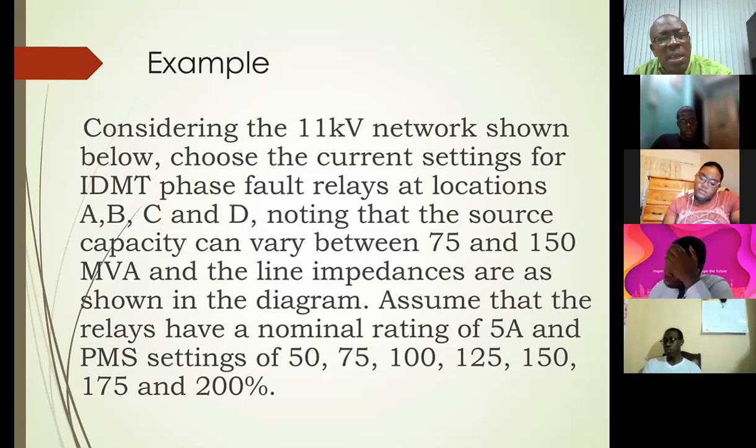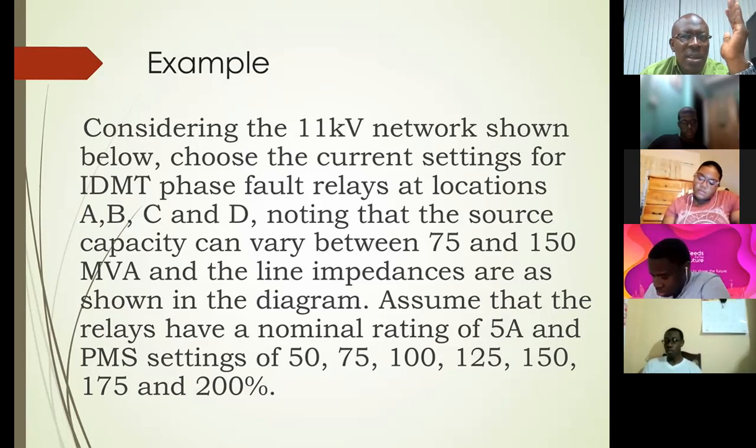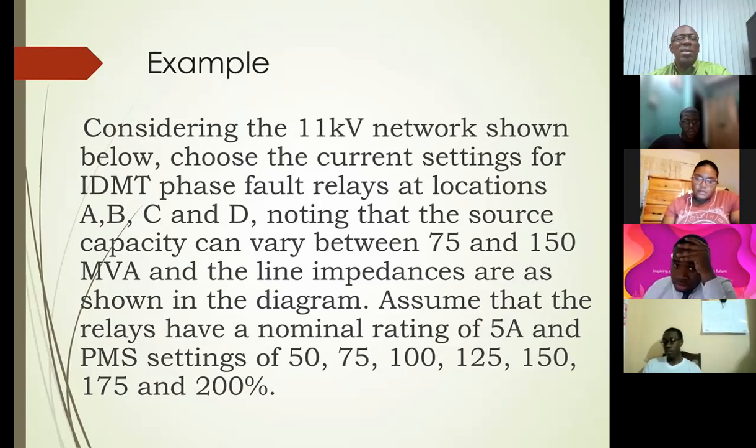We are giving it here on the secondary, but of course, if it's nominal 5 amperes on the secondary and you have a 100 to 5, then the nominal on the primary would be 100. Is that clear? So the nominal we are giving here is a nominal on the secondary of the CT. But in your case, and you'd agree that if I am dividing 5 million by 30,000, and I divide both the 5 million and the 30,000 by 20, I'm going to get the same answer.